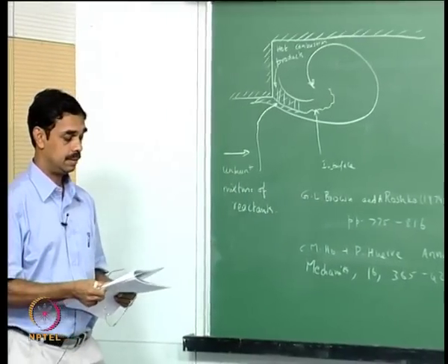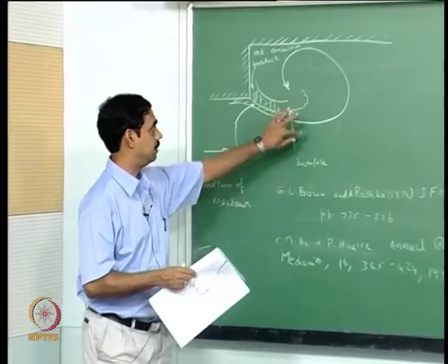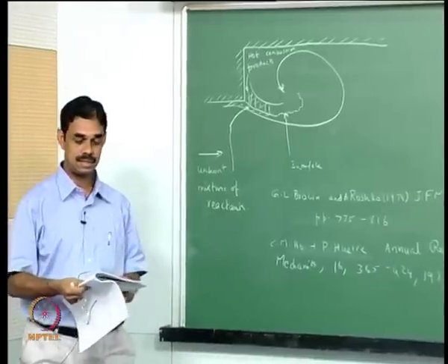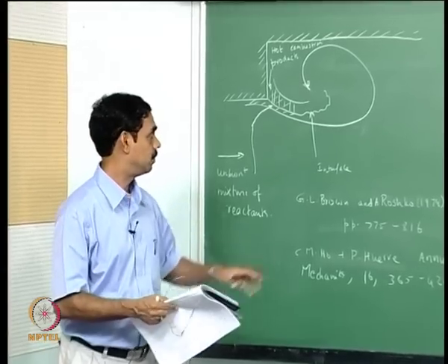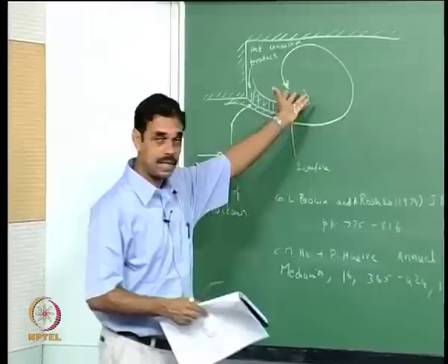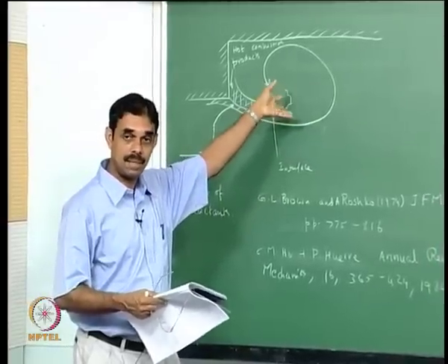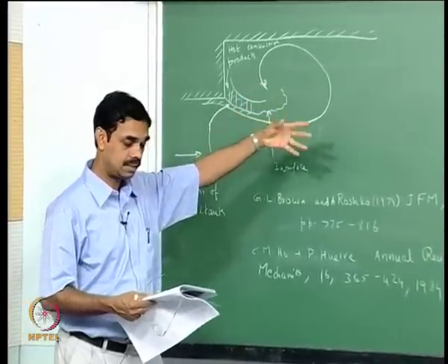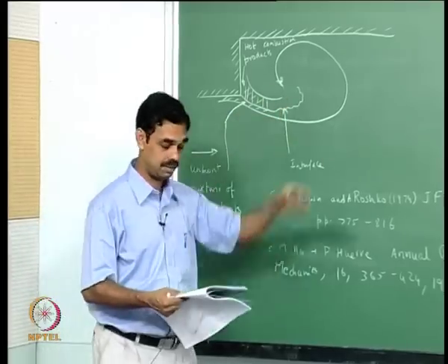However, the initial fine scale turbulence is limited only to this region, but it is conjectured that fine scale turbulence is abruptly enhanced during the roll up of vortices. When the vortex is rolling up, suddenly this fine scale turbulence increases, and therefore fine scale mixing increases, and therefore this suddenly causes the reaction to occur, and this is a periodic phenomenon.